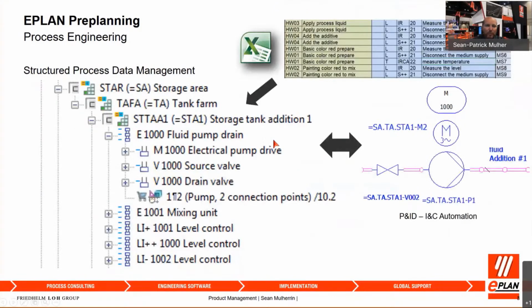The huge benefit of Pre-Planning is not only can you capture your graphical information in the design, so while you're creating your P&IDs, you capture information, but on top of that, you can structure that data within Pre-Planning. And you can see here you have your storage area, tank farm, storage tank edition 1, you've got your pumps, you've got your valves, you've got your level controllers, you've got your level indicators with alarms. So everything can be designed in a structured environment easily and conveniently using your graphical design.